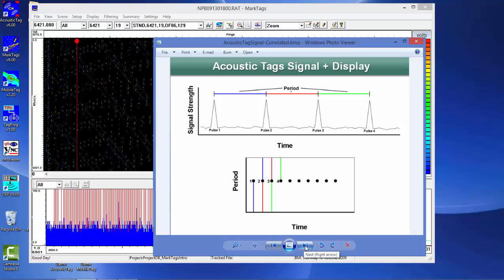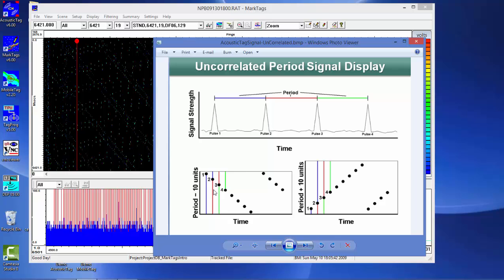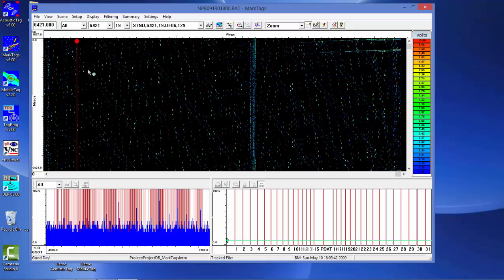If we have the vertical scale set for a different tag, we still see signals from another tag, but they will not be lined up horizontally, but in a diagonal fashion, since it's not set to the vertical scale that we currently have it set for. So in this case here, every time we change the tag ID here, it automatically sets the vertical scale of the main display to view signals at that specific transmission time.